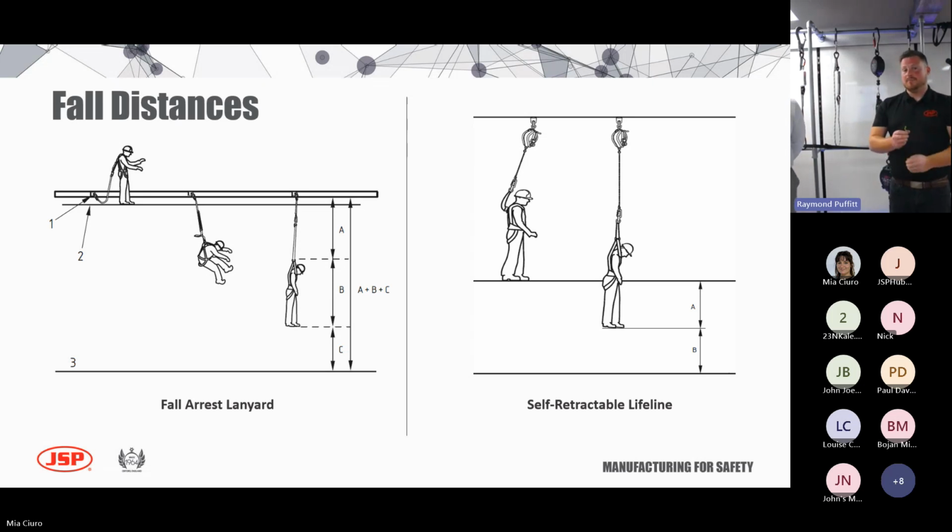So we saw how quickly the block actually locks, works like a seatbelt. So the user would step off, he would fall. He's going to fall probably 1.5 meters. We then think about meter of clearance, and we think we roughly allow for the user's height. It comes out about 3.5 meters, so it's nearly half the full distance between the two.